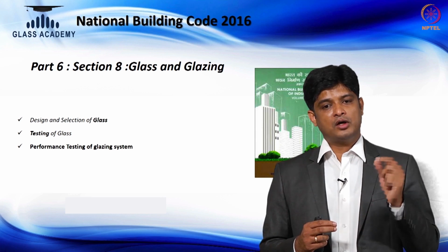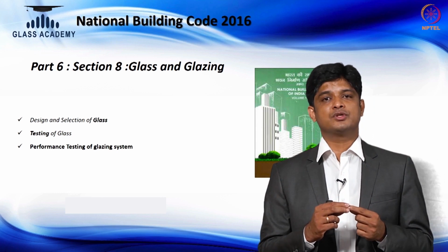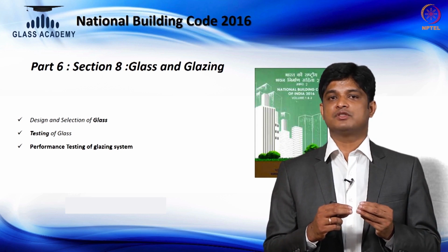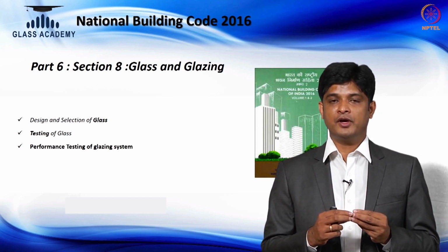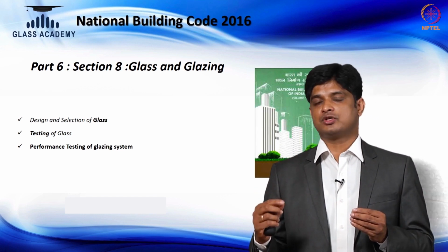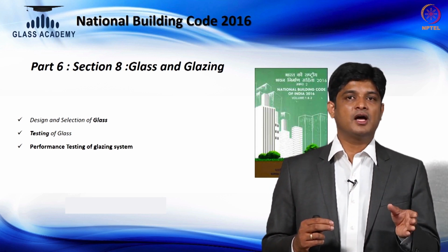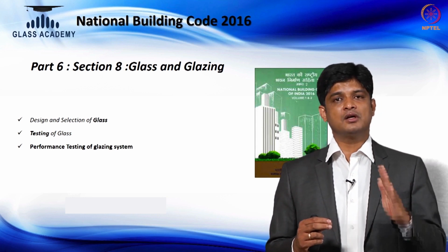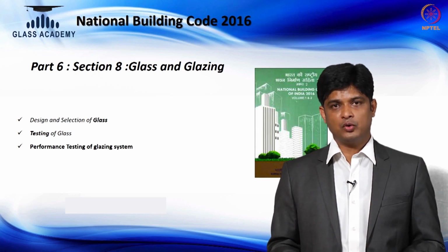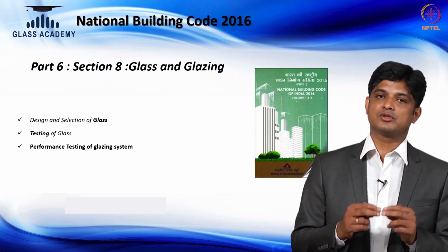To recap again, on the glazing side there are three important parameters to understand: light transmission, the solar factor, and the U value of the glass. These three important energy parameters have to be identified based on the orientation of the building, the window wall ratio, or the occupation of the building. Second is the safety requirement, which is very important. You have to understand the criticality of the location, whether it is vertical glazing, sloped glazing, a skylight or overhead glazing, or glass floors. Based on the usage or criticality, the safety requirements are defined.